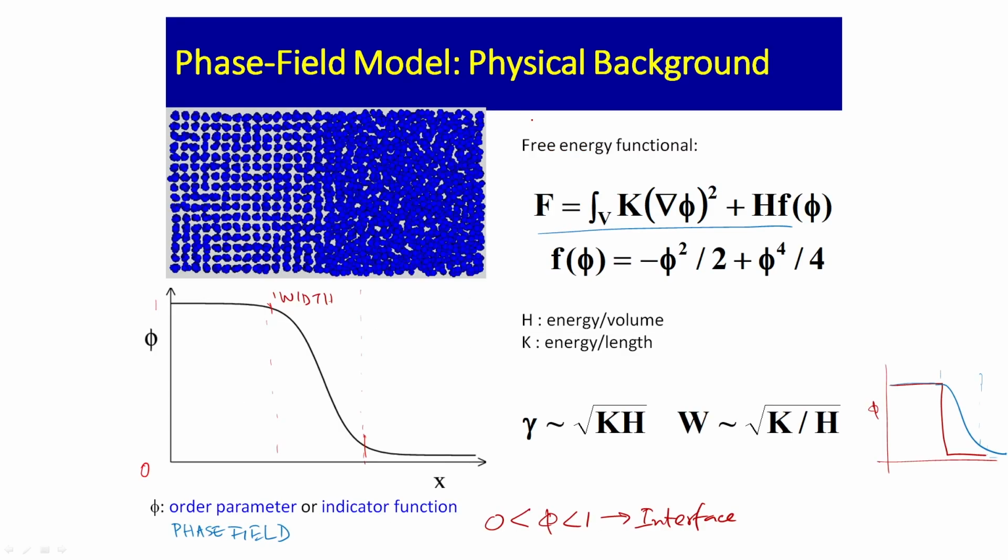And free energy is always approximated such that the total free energy is a volume free energy plus surface energy. An important aspect in phase field simulation is to assume the evolution of one variable, phi, as a function of time. Therefore, for the whole system, when you are talking about phase transformations, phi is allowed to vary continuously from one phase to the other phase via the interface, as shown here.